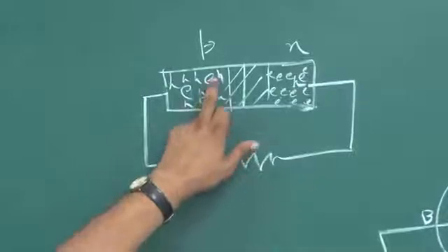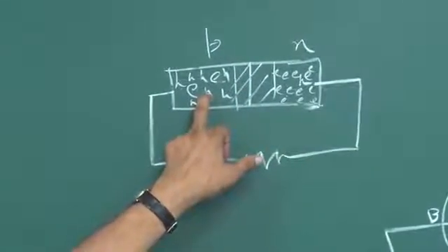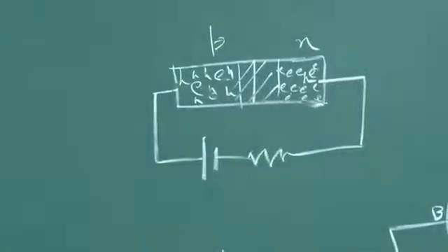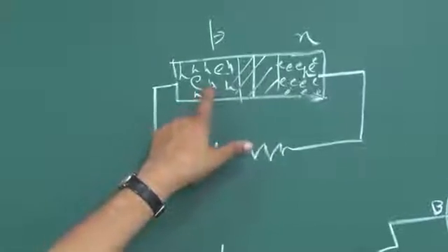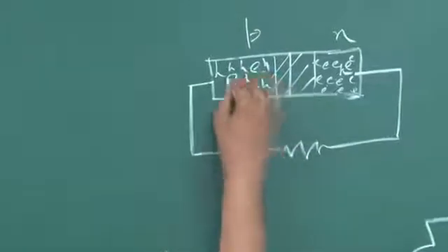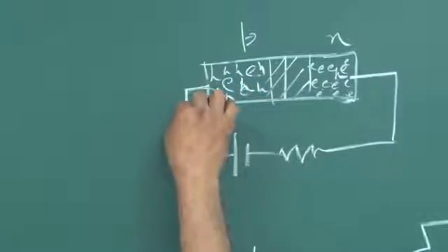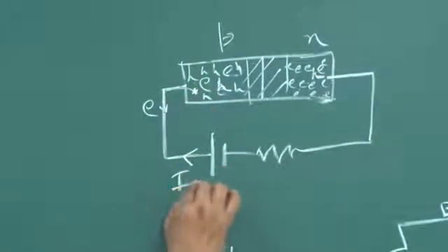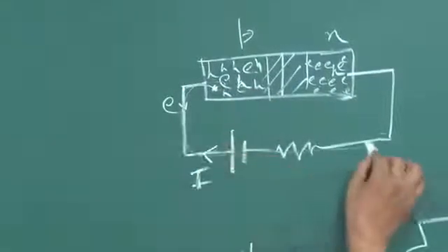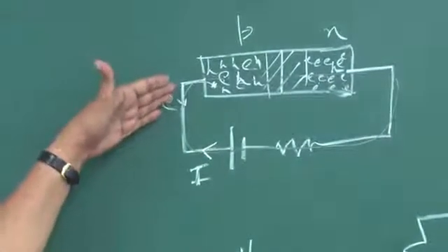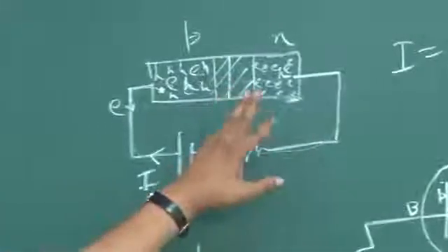And if an electron hole pair combines, the electron is coming from here, but the hole was there for all that charge distribution, charge neutrality, electric field, potential. This battery will maintain all those things as a function of time. So, if this hole is filled, a new hole should be created somewhere to maintain that charge balance, and that happens. Some electron hole pair will be broken here, and then that extra electron will flow through this, and therefore contribute to this current I which is going here. Okay. And of course, once the electron is here, it will go through this and complete the circuit, and that will contribute to IE. I is equal to IE plus IH. So because of these conduction electrons, you have the current.